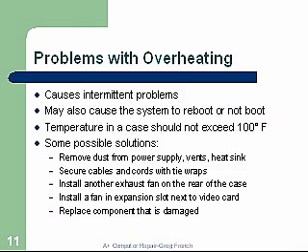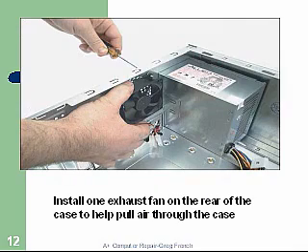Some problems and solutions: remove dust from the power supply, vents, and heat sinks. Secure cables and cords with tie wraps. Install another exhaust fan on the rear of the case. Install a fan in the expansion slots next to the video cards. The video cards put off a lot of heat. Replace components that are damaged. We're installing a second exhaust fan on the back of the case to help pull air through, keeping things a little bit cooler.